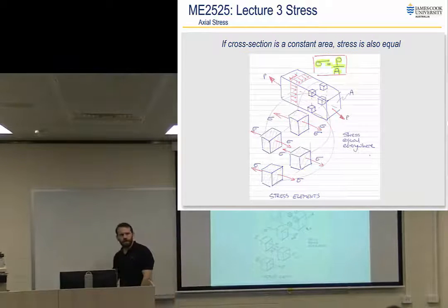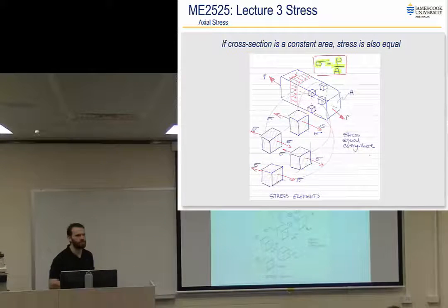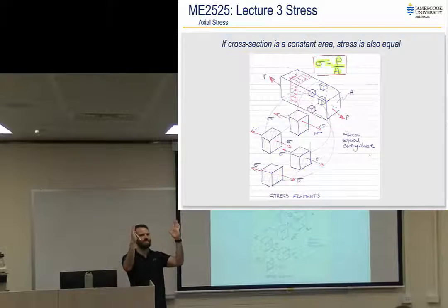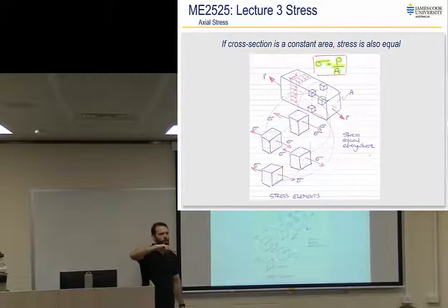Now, is that different if it's a circular cross-section? No, identical. What about if it's an I-beam? Identical, doesn't matter. Axial load, so long as it's not unevenly distributed. If you apply it through a bolt hole or something, you might have some sort of a different curve, but if it's assumed to be evenly distributed on each end, it doesn't matter the cross-section, wherever the element is within it, it will have even stress, sigma equals P divided by A. Cool? That's the easy one.